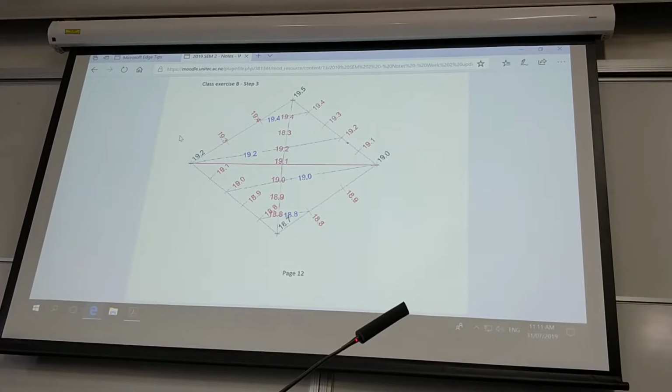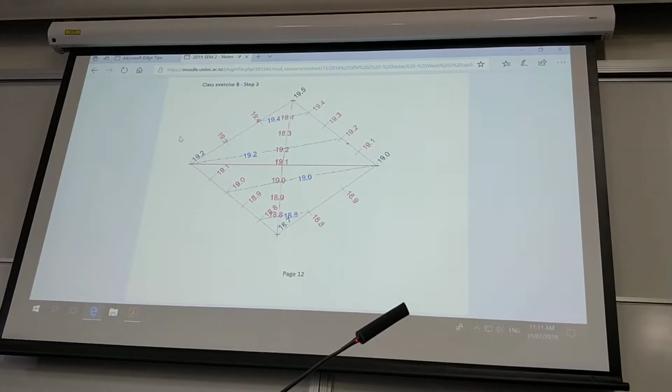So the way I do it is I draw a profile of this, and I do a triangle, which means the level in the profile view, or a section view. And the level over here, of course, is 43.81. And somewhere over here is going to be where the contour crosses at a level of 44. We know that distance there is 20.2.